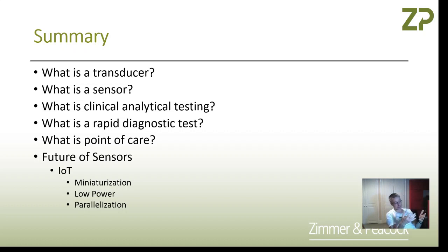Basically, if I have 20 sensors, and they're in a similar environment, then I'm expecting 20 signals telling me a similar thing. And that's really good because it gives me redundancy. Because if one of them breaks down or goes wrong, I can see that one sensor is out of family with the other 19 sensors, and as a system, it will carry on working.